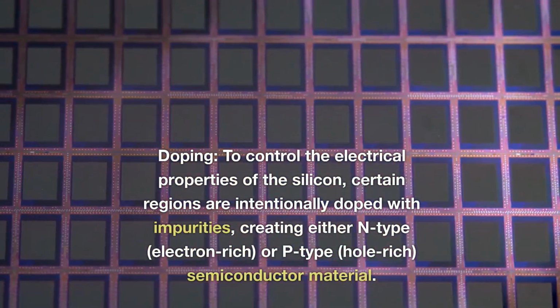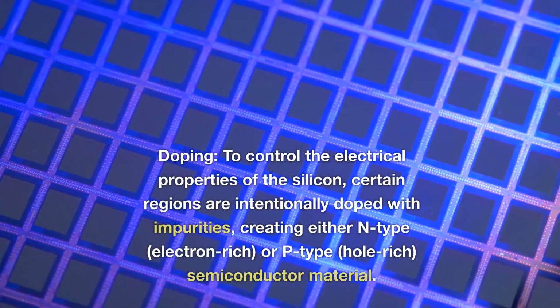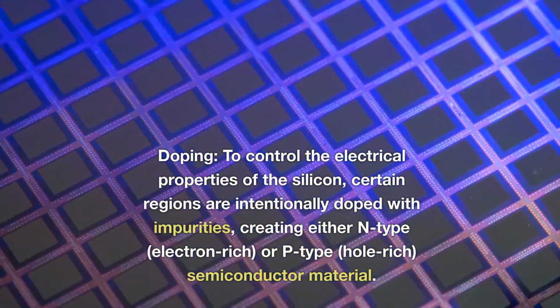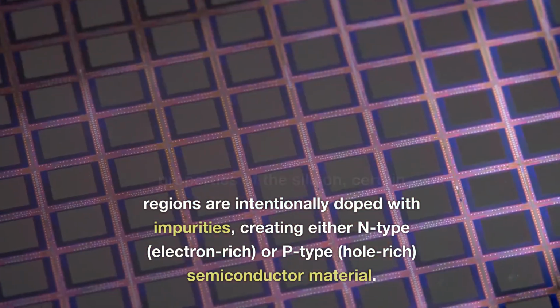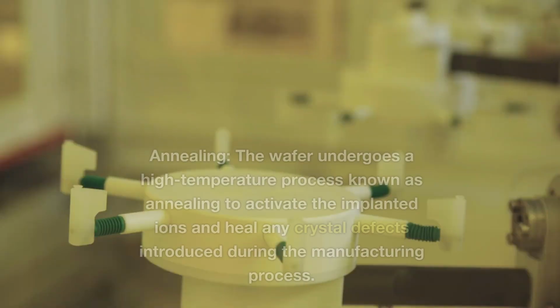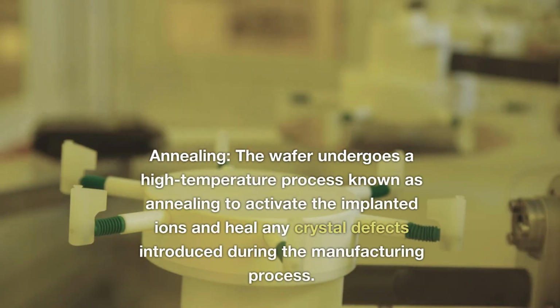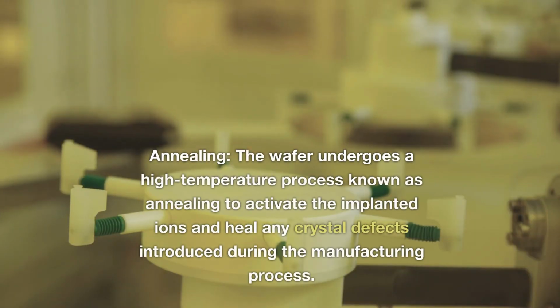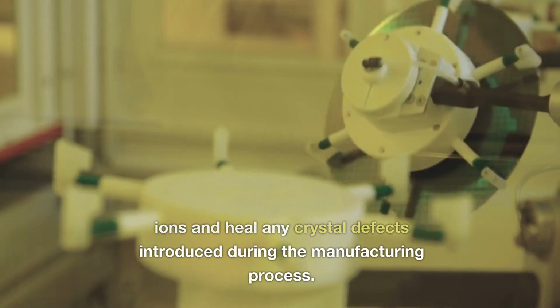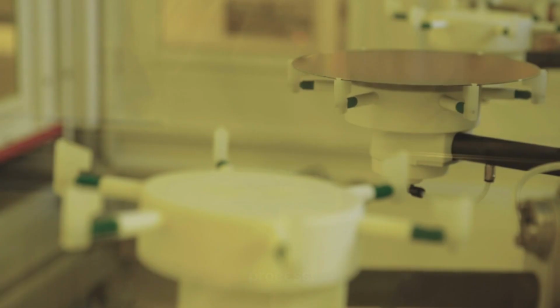Doping. To control the electrical properties of the silicon, certain regions are intentionally doped with impurities, creating either N-type, electron-rich, or P-type, hole-rich, semiconductor material. Annealing. The wafer undergoes a high-temperature process known as annealing to activate the implanted ions and heal any crystal defects introduced during the manufacturing process.